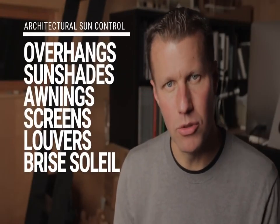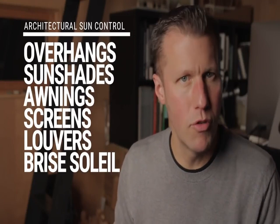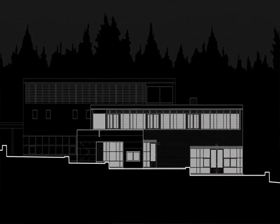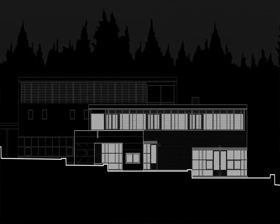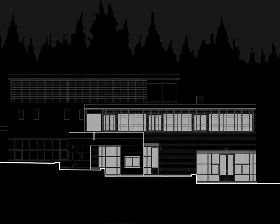Horizontal elements can include an overhang, a sunshade, awnings, screens, louvers, or brise-soleil. Because our design was so linear, horizontal louvers seemed the most appropriate. Now, we could have just matched the coursing on the siding and called it good, but there's more to it than that. The spacing and depth of the horizontal louvers can be tuned to your exact geographic location. Why not, right? This is where the sun charts come in handy.